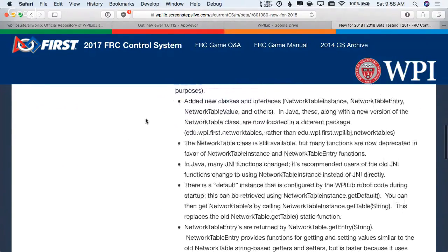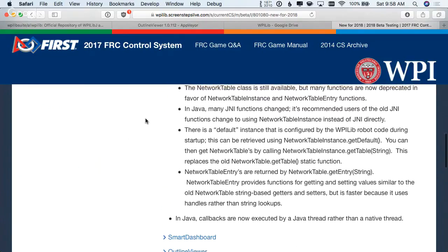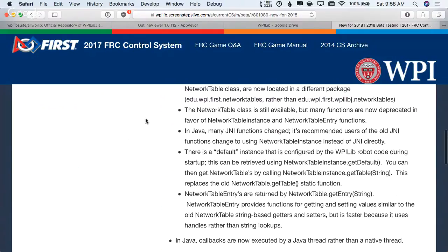So now you can take all the data and pack them into one message, okay? And then it guarantees you either get all or nothing. So it's all there, it stays in sync. The problem that you always have with real-time programming is you send the X value, and so the robot now has a new X value and the old Y value, and it starts aiming its shooter or something based on the new value of one part and the old value of the other part, and it obviously doesn't work. So there's stuff to let you pack things into one package and then send it all at once, so you guarantee that what you have will always be in sync.